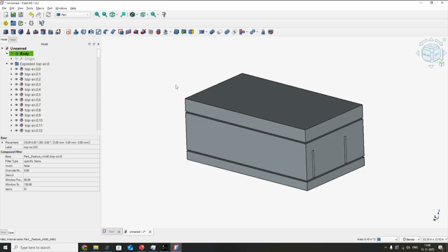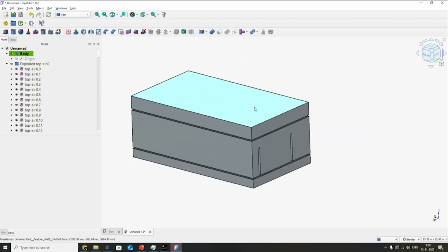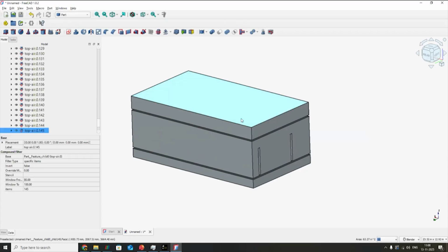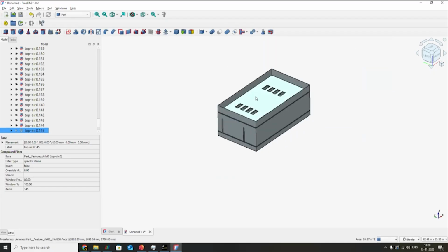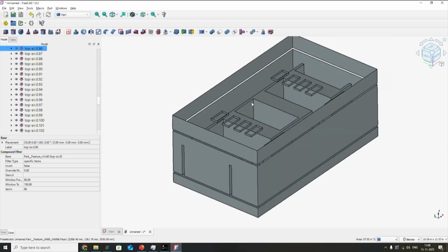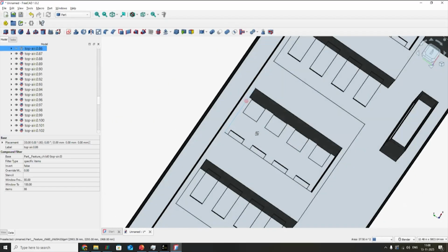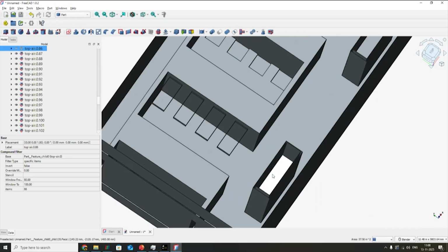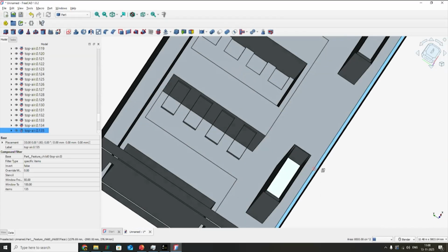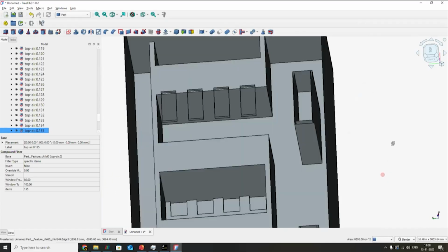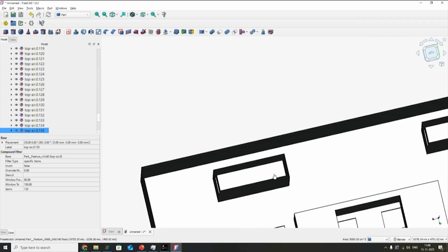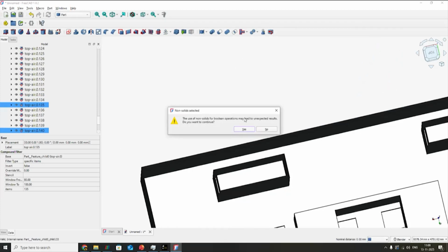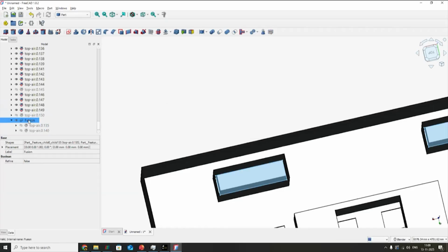So now we just need to name our boundaries. So I'll name inlets and outlets. I can select any face and press space to hide it. And this way I can hide the ceiling. And now we can see inside the room. So here we have the CRAC inlets. So I'll select this face. I'll press Control on my keyboard and select the other inlet face. So both are selected. And we'll use this tool, union, to make them into a single part.